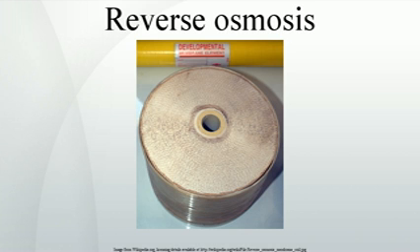contamination. Membrane pore sizes can vary from 0.1 to 5,000 nanometers, 4x10^-9 to 2x10^-4 in, depending on filter type. Particle filtration removes particles of 1 micrometer, 3.9x10^-5 in, or larger. Microfiltration removes particles of 50 nanometers or larger. Ultrafiltration removes particles of roughly 3 nanometers or larger. Nanofiltration removes particles of 1 nanometer or larger. Reverse osmosis is in the final category of membrane filtration, hyperfiltration, and removes particles larger than 0.1 nanometers.